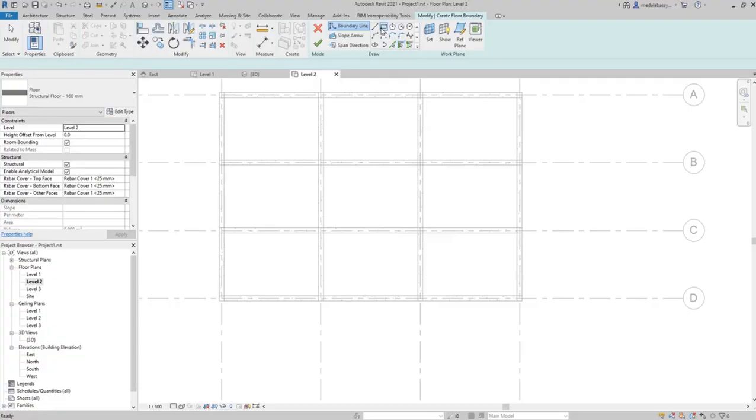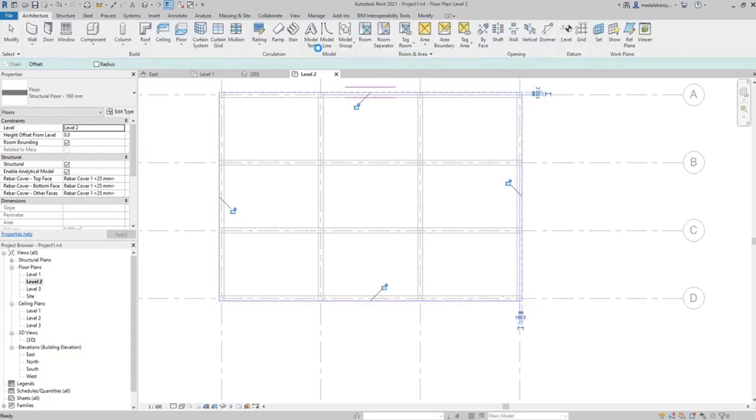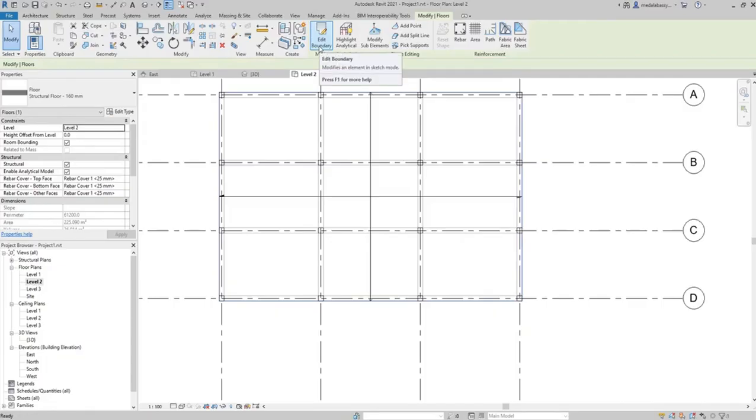We'll do the same way, so need to select the rectangle option from one corner to the opposite corner on the other side. Yeah, just click on the green tick icon to finish it. So we have the slab. Now we can just select it,